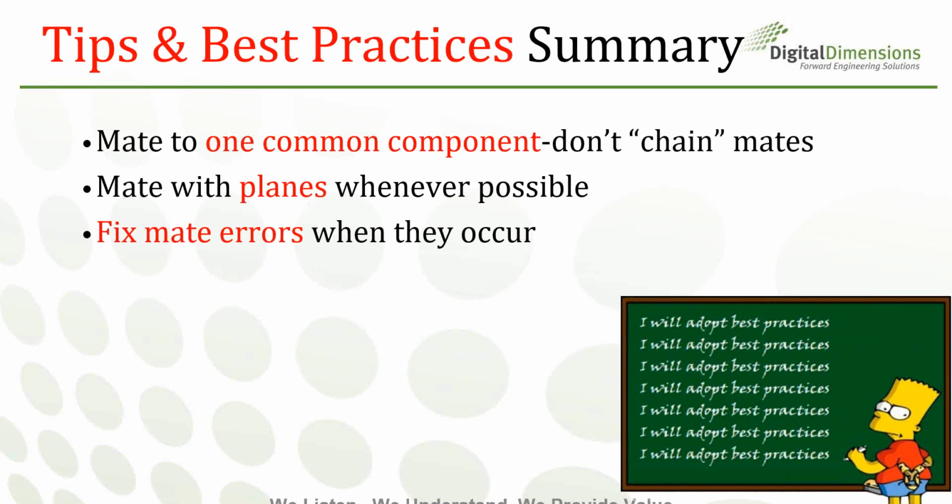Fix mate errors as they occur. So if you get a mate error, just go in, figure out what you did, and fix it. Don't pass it on to the network and let someone else open it up and see all those red errors and cautions. That's not fun.